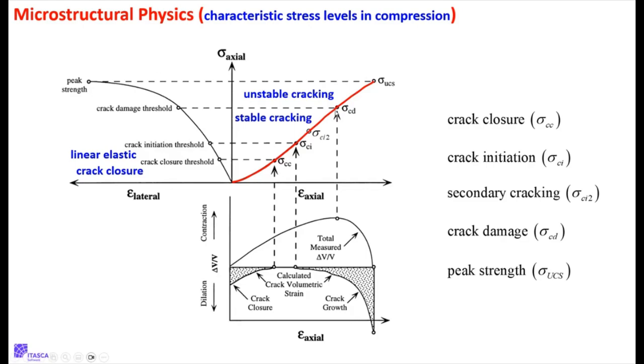Okay. And then if you keep doing the test, you eventually reach a peak. I don't show the rest, but this is typically quite brittle, and it'll reach this point, and then it'll go like that. It'll just drop down. And that's where you need to put on your safety glasses, because that thing is often going to explode.